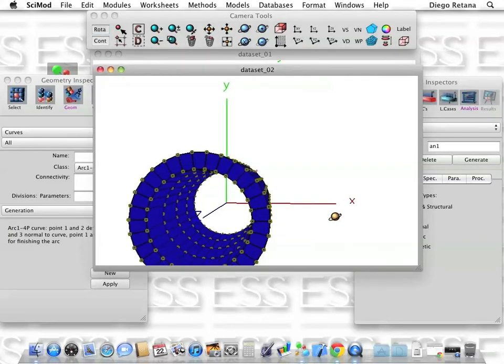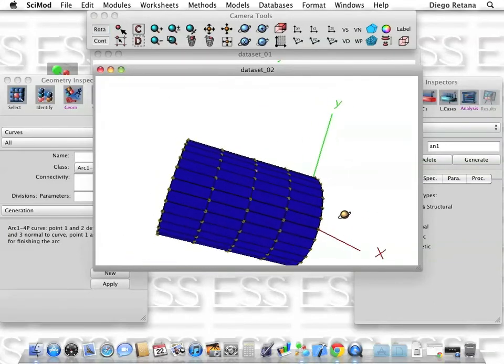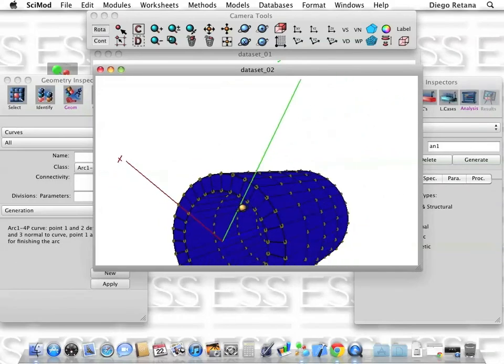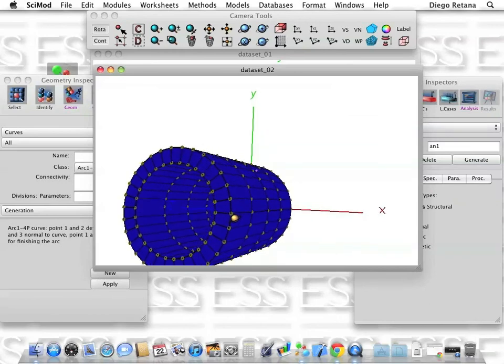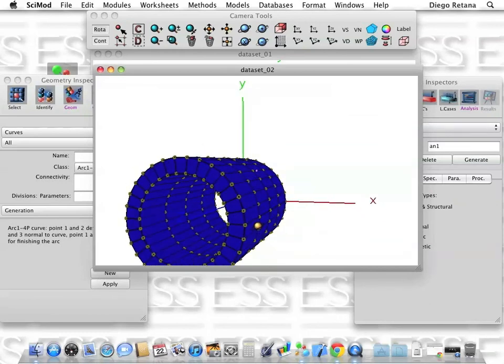A very important thing to keep in mind for cylinder and spiral mesh is that the last set of nodes in the process of iteration are replicated. A sweep selecting those nodes is required. So select the View Contour icon and you will see the replicated line.